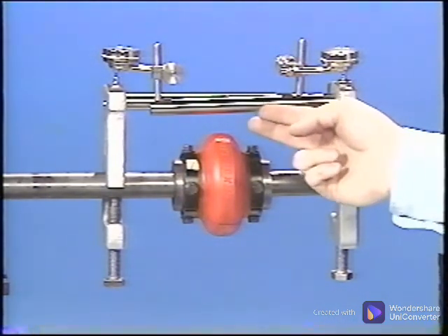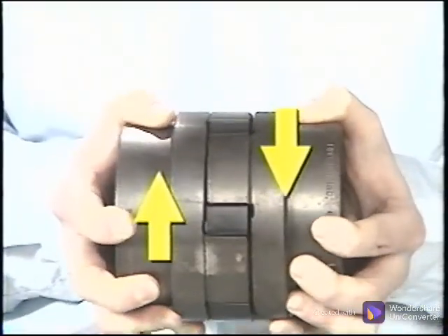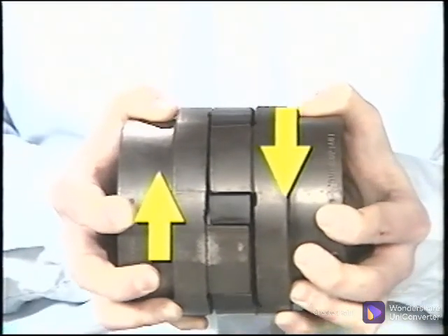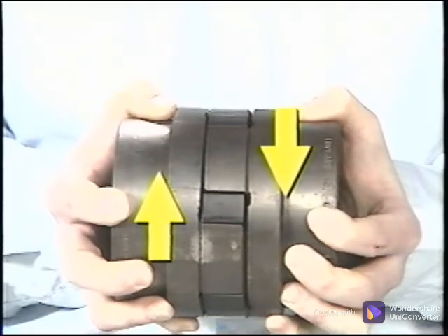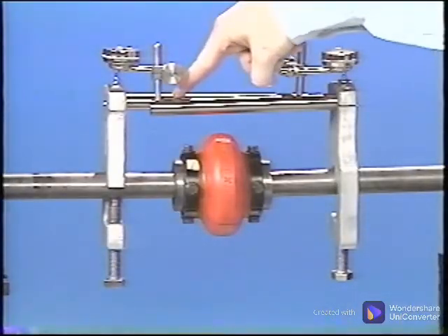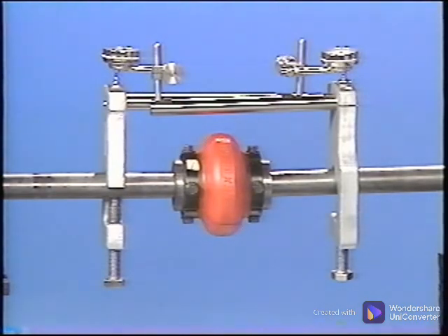Axial movement does not affect the measurements, because the dial indicators do not measure in the axial direction. However, if the coupling has any torsional shift as the shaft is rotated, then error will be induced into the reading, and the bar holding the dial will have some amount of sag that needs to be compensated for.